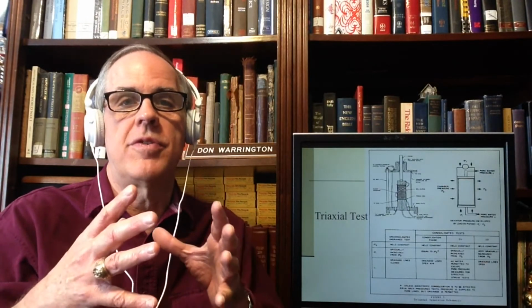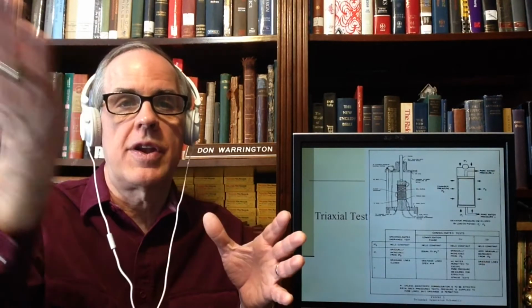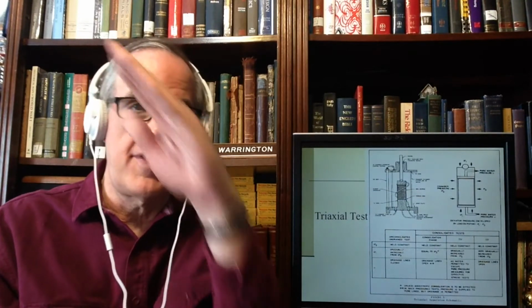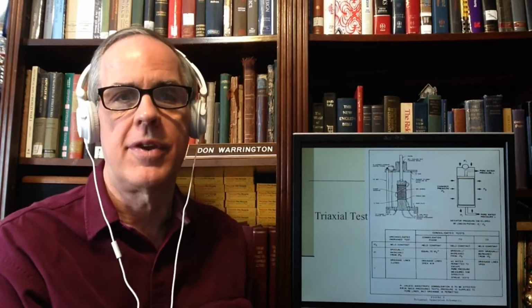And failure usually means it bulges out, or it can go across the old 45-degree thing where it fails, plain like that, and you have failure. The thing that has changed most often is the drainage. So, for example, you'll notice in sigma 3, which is the confining stress, it's always held constant during this test.